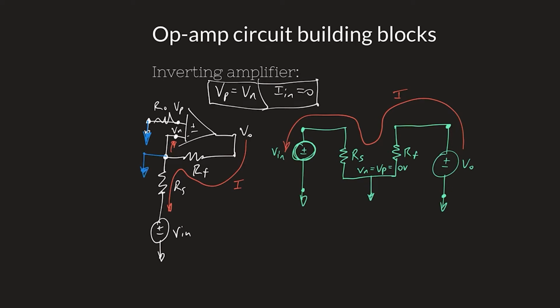So I could have drawn this anywhere. I could have drawn it up here. It doesn't matter where I draw it. It's just a label. It's just saying it's grounded. It's 0 volts right there with respect to the rest of the circuit. But just because I've drawn this in here, it doesn't mean that I can allow a current to go through there. I can't just arbitrarily start sending currents through labels. Same thing here. I can't just arbitrarily send a current through there.